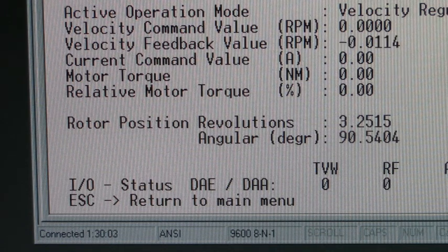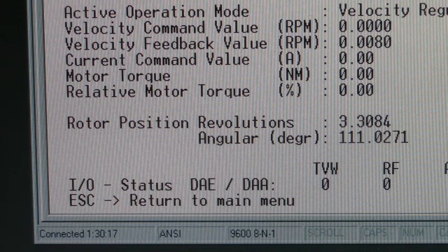Get in there and see. There we go. Okay, turning on the power supply to apply plus 3 volts to A1 and ground to A3. Let's see what we have. We have 111.282. Let's write that down.